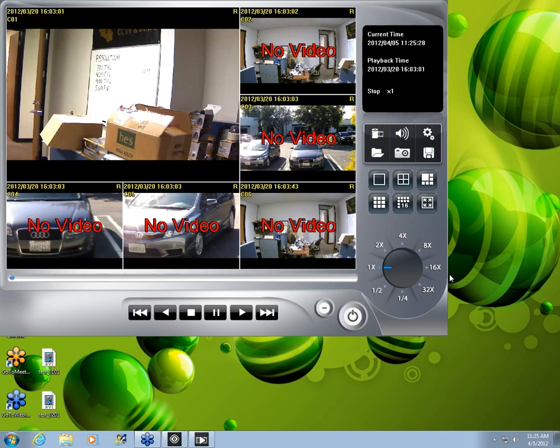Okay, so what Robert was asking is, is there a smartphone app? Yes, there's many smartphone apps out there that can connect to the individual cameras. What our cameras use is an ACTi encoder, which is compatible with almost all apps out there that support our cameras, because we use a certain encoder, the Q7401, so that becomes very compatible with all the applications out there. So there's many free ones, and there's some paid ones that have more advanced features.